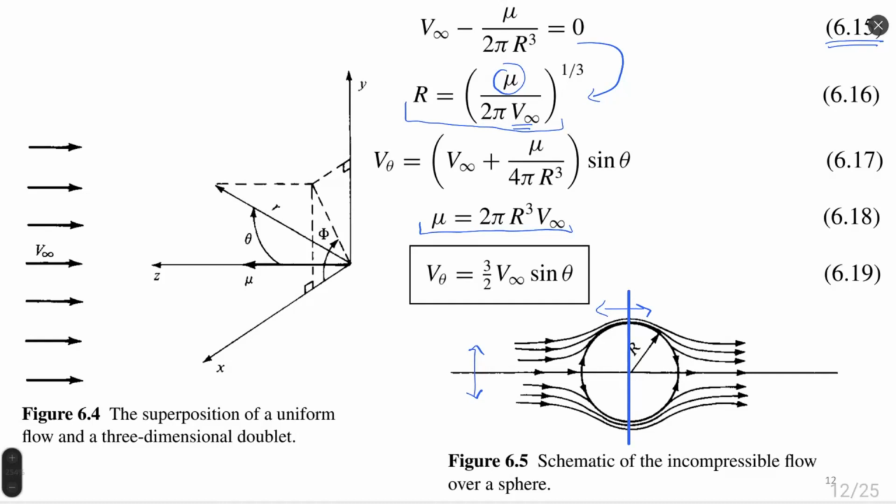So there is horizontal and vertical symmetry of streamlines. It means that since horizontal symmetry exists, lift would be equal to 0, and since vertical symmetry exists, drag associated with pressure would also be equal to 0.